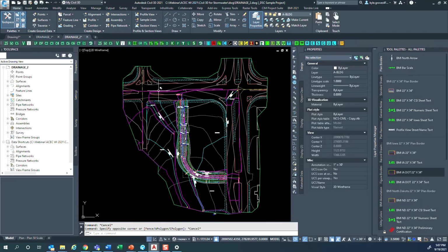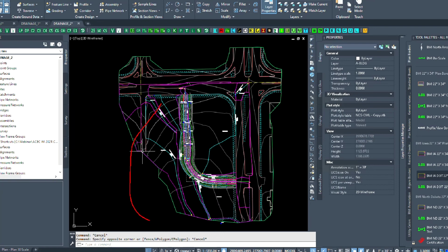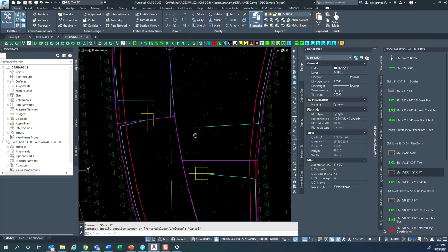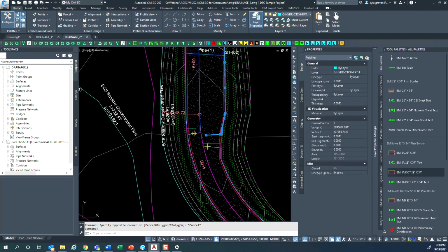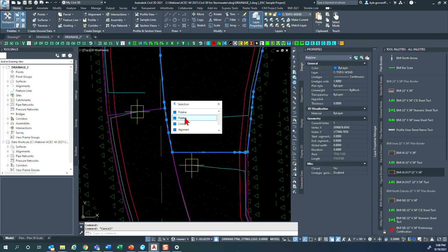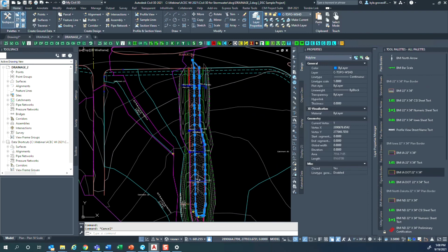So I went through, I've got catchments going for most of my site, basically clockwise from like 11 o'clock through here. My two outstanding ones are going to be the east and west half of my road in the north half of the site. As I zoom in here, I can see I've got a couple of polylines that don't have that little yellow marker. These are my water drops that I had created previously, and I've also got that light blue polyline representing the outline of my catchment area.